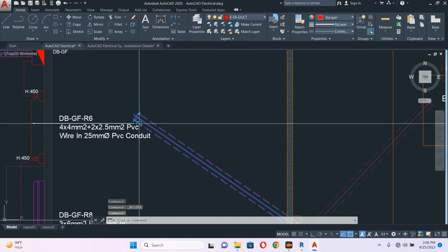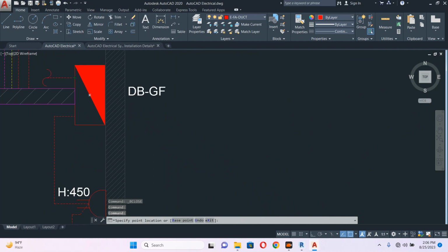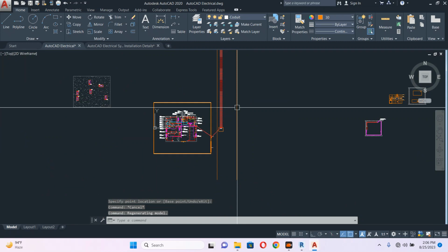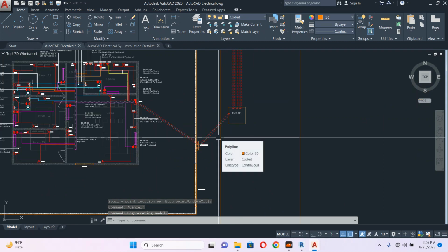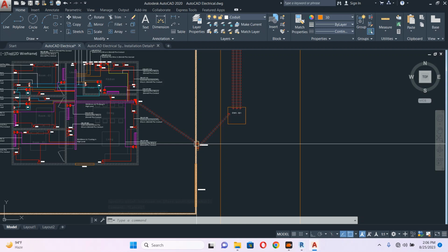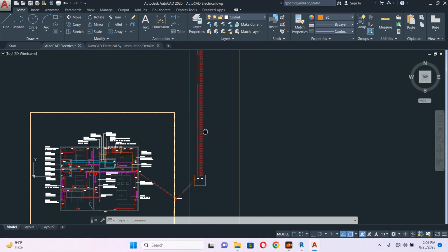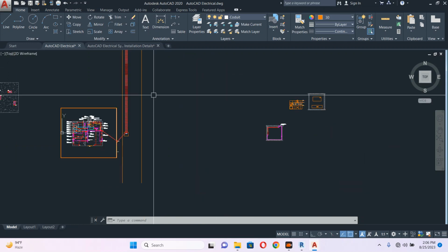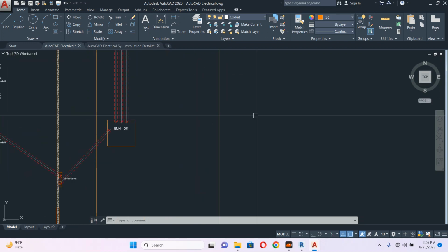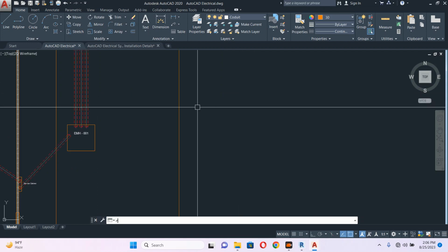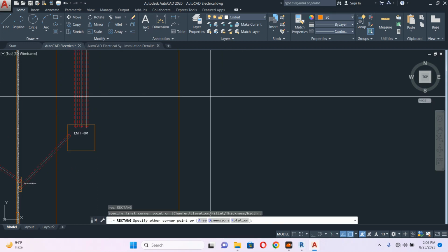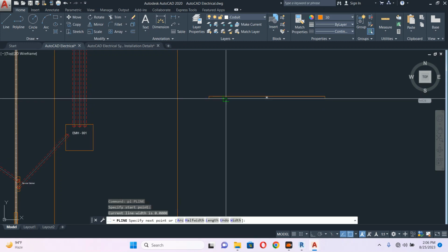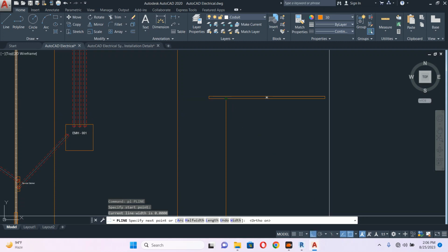Okay. So this is how it will work. So the termination will come here. This duct will come 600 mm below road level. So let's draw a section somewhere here. Let's consider this one as a road. Okay. Then from here around 600 mm below, our duct will start.